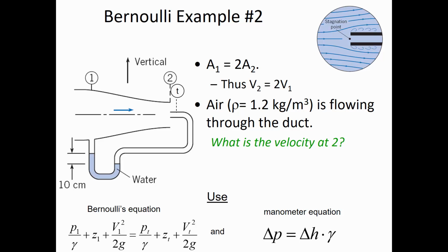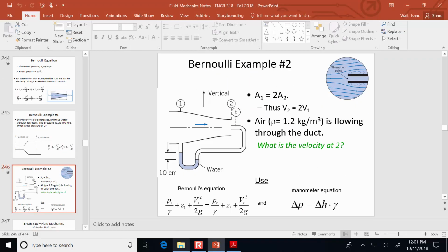So we're using 1.2 kilograms per cubic meter, because that's the fluid that Bernoulli's equation is being applied for, to the 1/2 power. So what you get when you crunch all those numbers is 40.4 meters per second as the velocity at location 1.